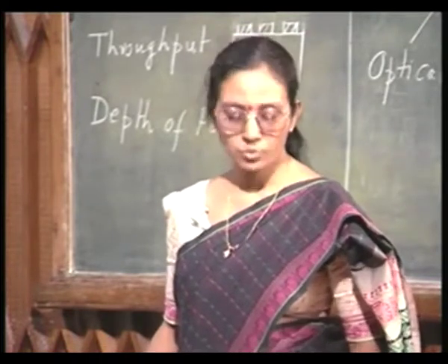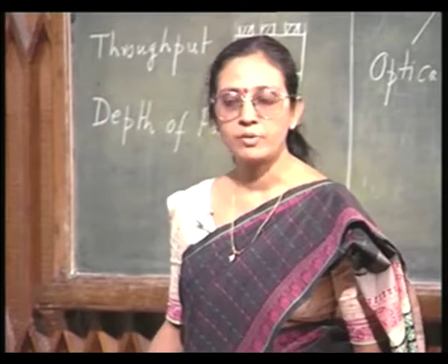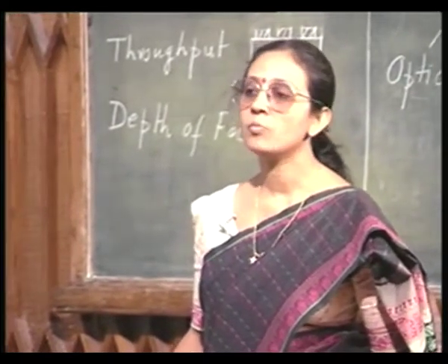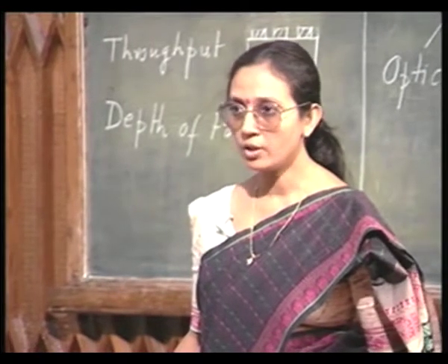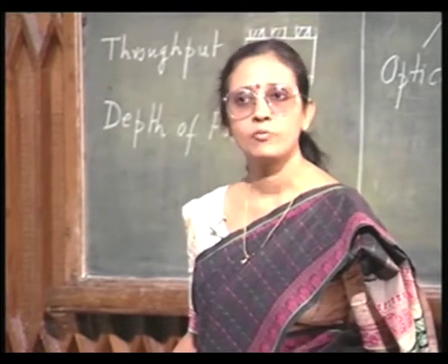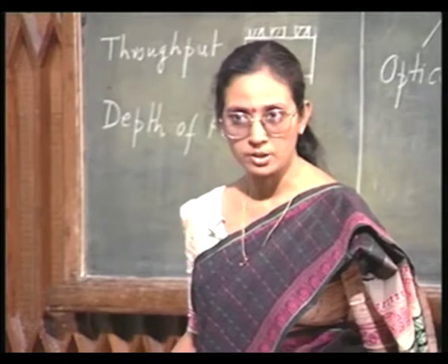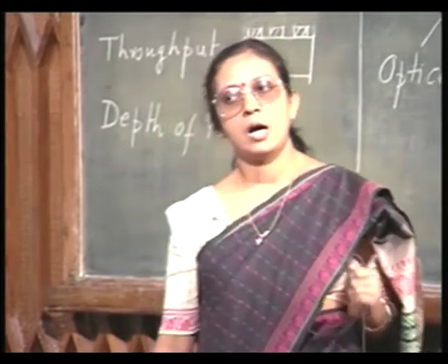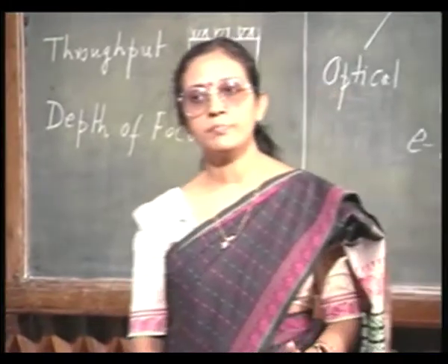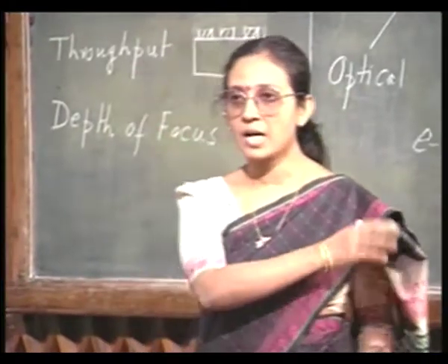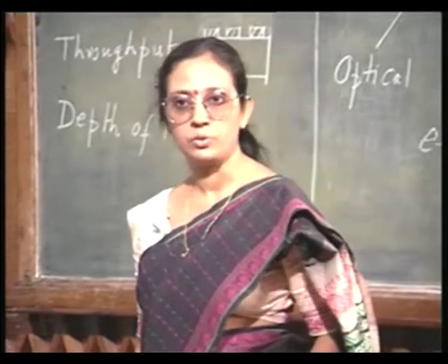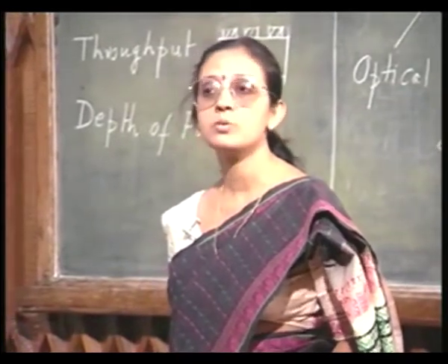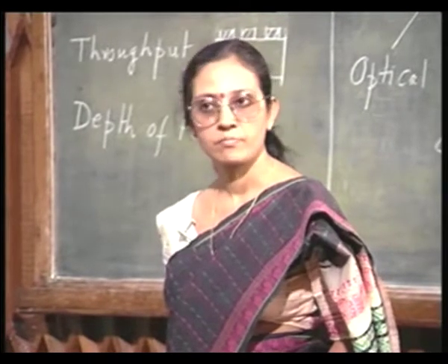We will start with the optical lithography, because even now, even today, that remains as the most popular technique of lithography, and it is obviously the oldest technology. In optical lithography, the steps I have already outlined to you. It follows these 4 basic steps. The radiation that we use is UV light.